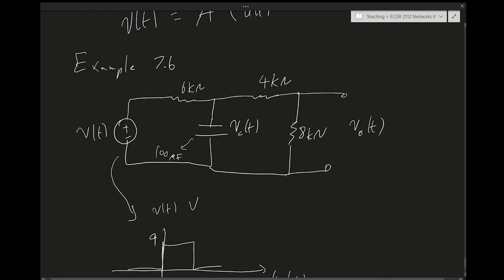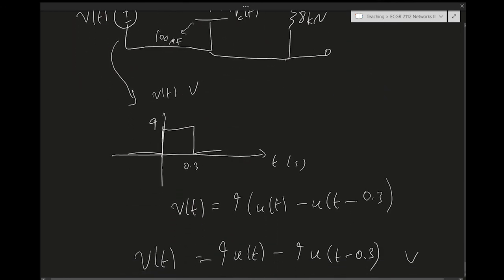Okay, so the techniques that we learned up to this point apply even though you have multiple events happening. It's just like I said, you have to take it one by one. You first find the transient in this region, and after you find it, you have the initial condition for the transient in the next region.